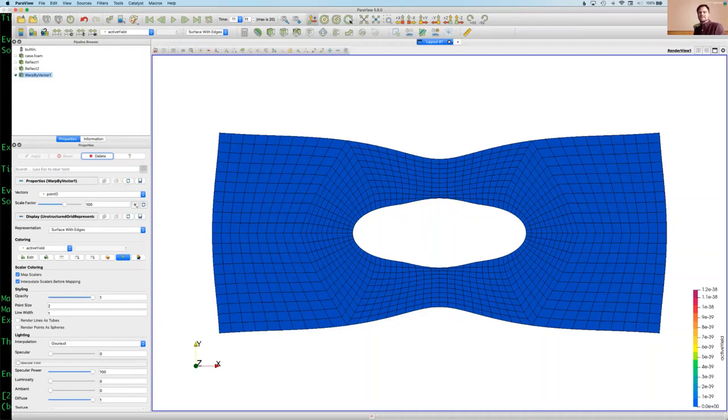However, it would still be an implicit solution algorithm, so it may not be the most efficient way, because each time step might be expensive to solve. Even though for a segregated solution algorithm or an iterative one, it may actually not be that expensive. So what about actual explicit methods? In finite element analysis, for crash or blast problems, you really use explicit finite element procedures.